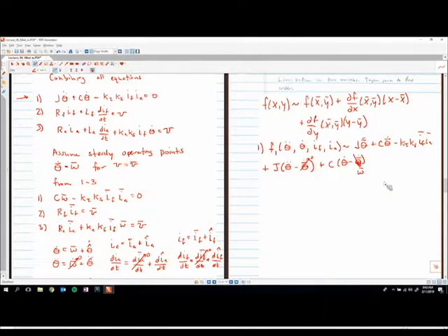All right. Next variable is IF. So we take the partial of this function with respect to IF. That's going to give me negative K tau Ks IA, and then I evaluate this function at our operating points.